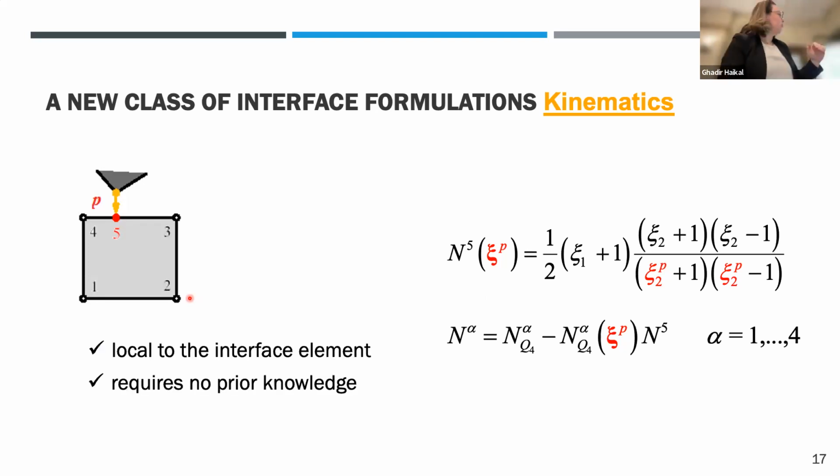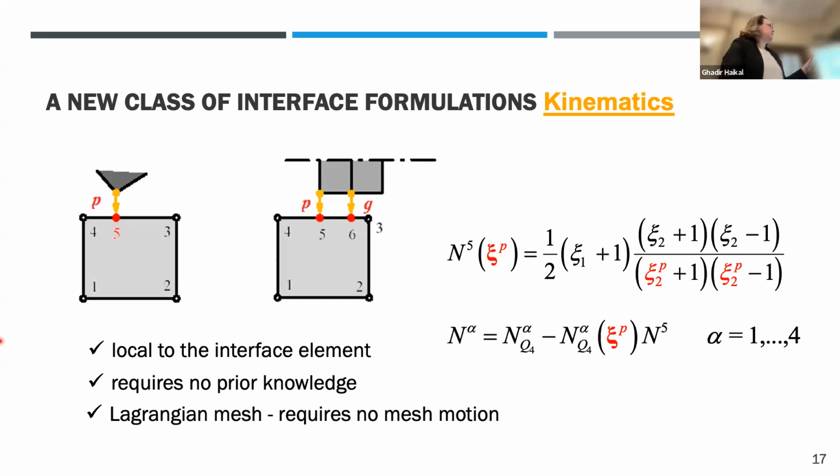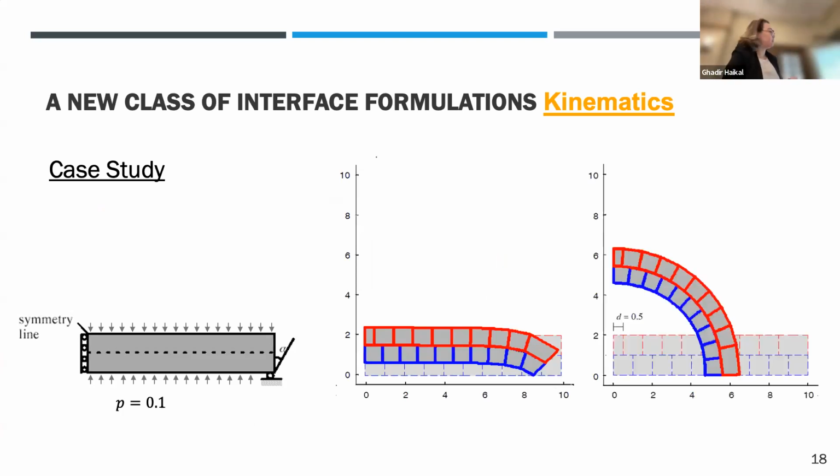When that happens, the interface enrichment increases the approximation order on the surface. It makes the solution more accurate on the surface, and it doesn't interfere with the approximation elsewhere. That's why you can still use it in existing software. You can do that as many times as you want. If you have multiple enrichments, that makes the solution even better. Formulation-wise, this fits within the finite element solution that we have currently. And you can see the effect on the problem that I just mentioned. If I implement this solution, then I get the pure bending mode that I expect.